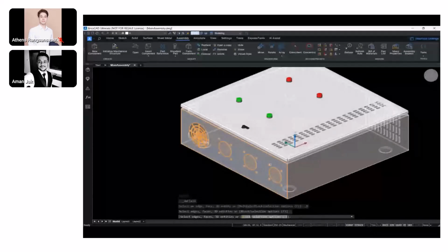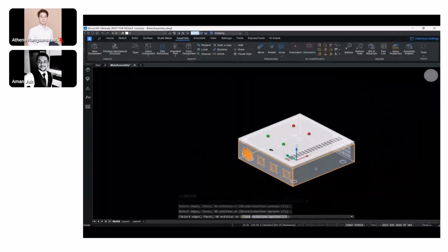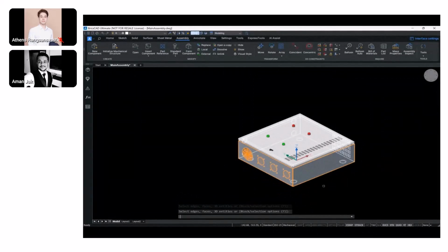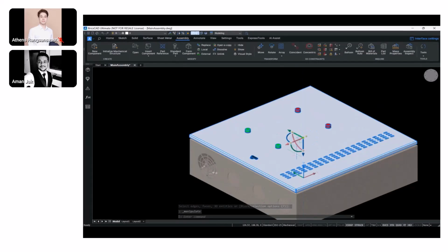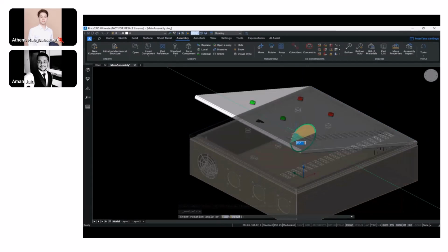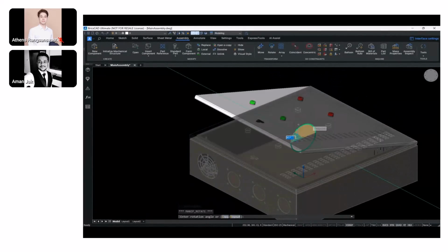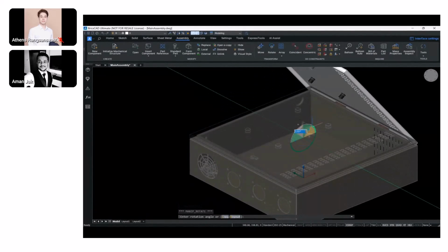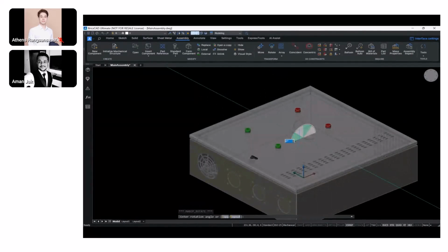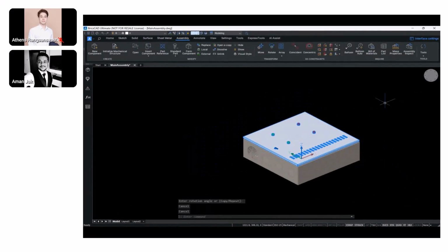Because it's translating in the x-axis, we'll fix one or both of these faces once again, so that now when I'm trying to rotate the door across the hinges, across this particular axis, okay, now it's steady. So now I can see the body does not translate when I'm trying to rotate the door, and it's perfectly mated. So this now completes our assembly.